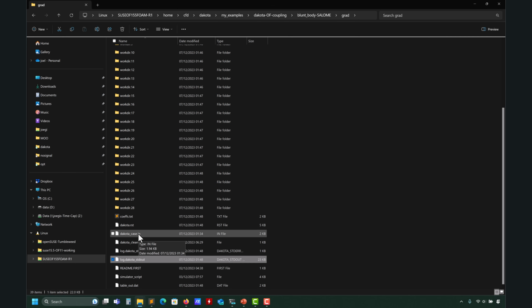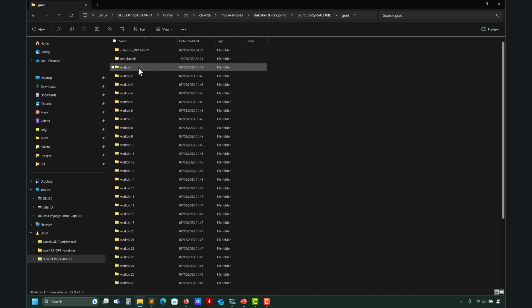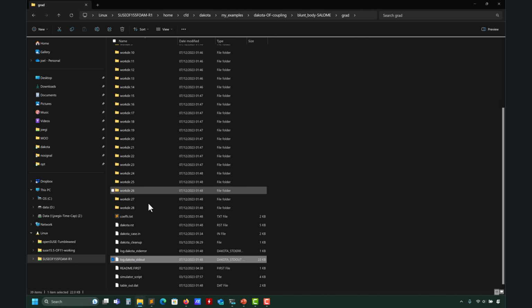If for some reason your simulation crashes, let's say at function evaluation 17, that information is safe here. So you can say, okay, restart from 17 and keep iterating. You don't need to do everything from scratch. And also you have all the trace saved there.